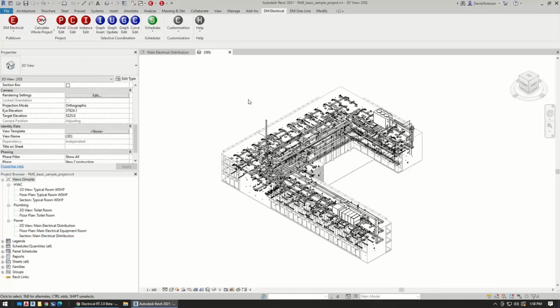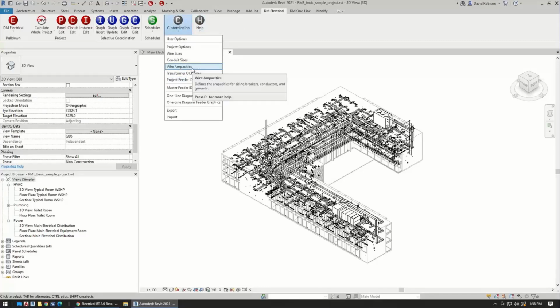Okay, current. And then secondly, if I go to a custom overcurrent protection size, like a 500, sometimes we use 500 amps or 700 amps, which most people don't do, but we've got weird instances. Are all the wire size things you just went through pretty much right? It's just a different size from the 400, 600, 800 kind of deal, right?